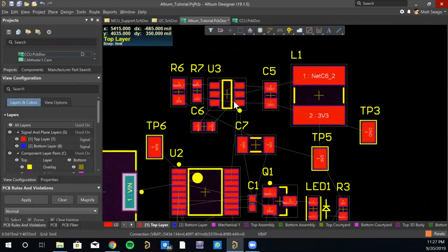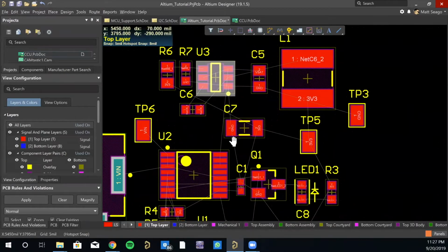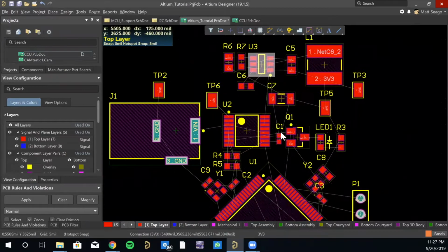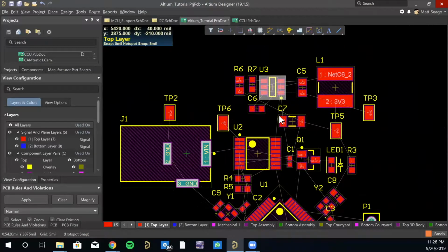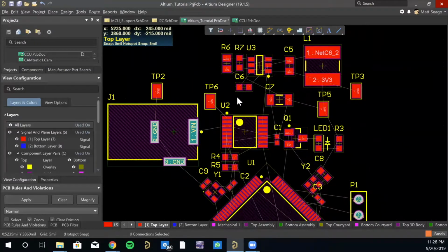Now, this up here for the voltage regulator is this whole chunk here. You need to go look at the data sheet for the chip you chose and look at the layout it requires you to do. It's going to involve you doing some goofy stuff with some power planes and all that good stuff, but you need to follow it verbatim. Okay.